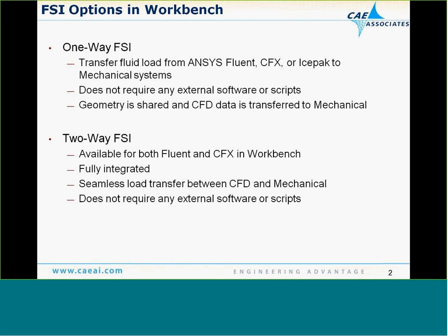So for ANSYS CFD, both Fluent and CFX can be used in coupling with Mechanical for two-way FSI calculation, and it's fully integrated, seamless load transfer with the data mapping between the selected surface pairs in the CFD model and Mechanical systems. So it does not require any additional software or external scripts to make this happen. So come back to the one-way FSI coupling scheme.